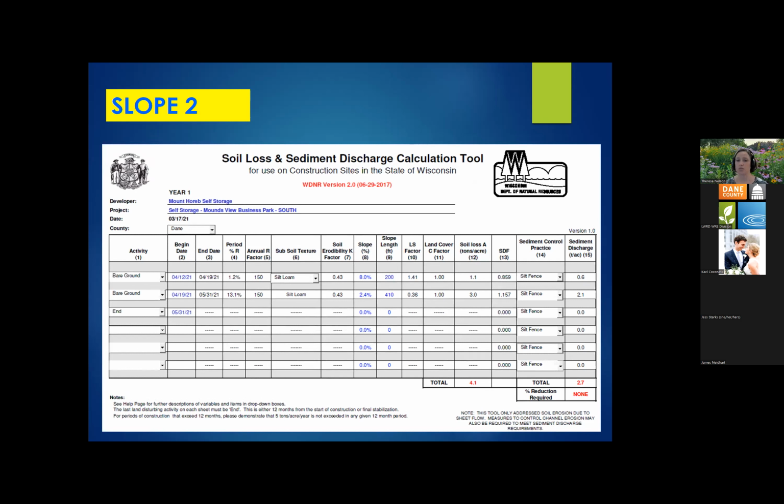That end could also be when the gravel is put down, when the base is put down, not necessarily waiting until the pavement, because gravel is considered a stabilization measure as well.